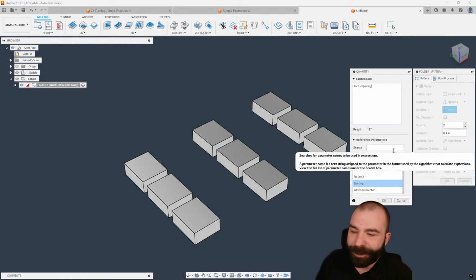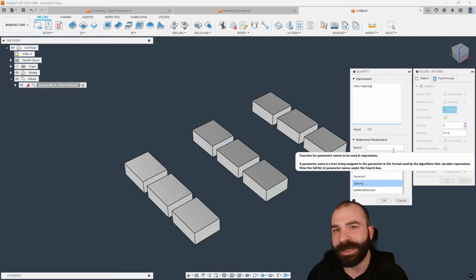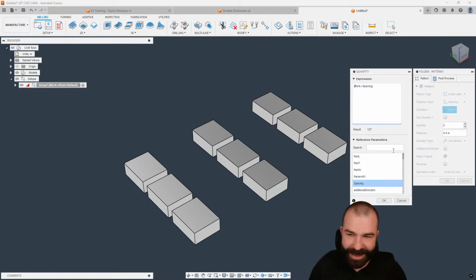So this is probably one of my biggest complaints when you start to deal with expressions, is the fact they all come through in millimeters each and every time, no matter what it seems to be on the side. So again, what we need to do is throw that possibly in some brackets and times it by 1 inch. And in this case, we get an invalid expression. Why are we getting an invalid expression? Well, it's because yours truly, based on a number integer, again, this is where we talk about a unit versus no unit type of setup.